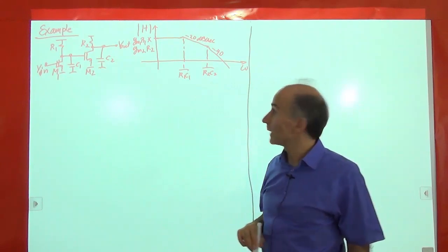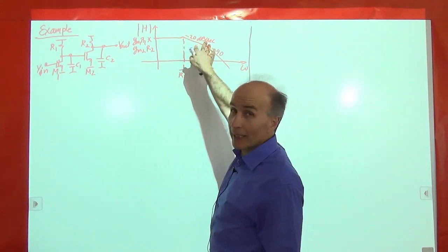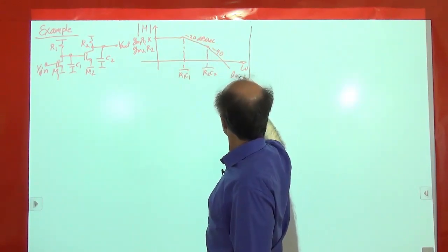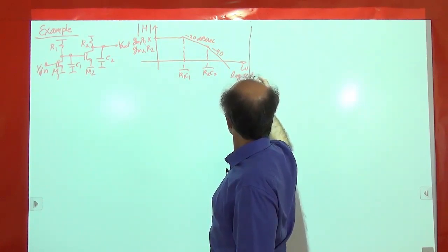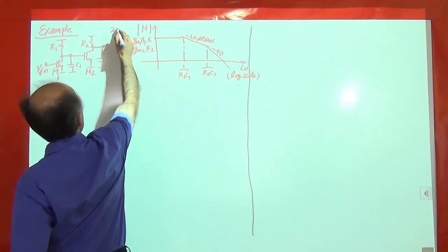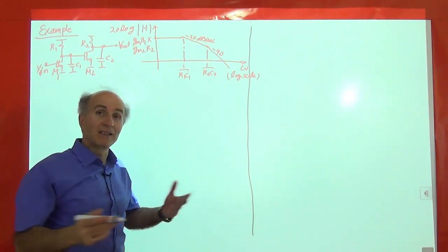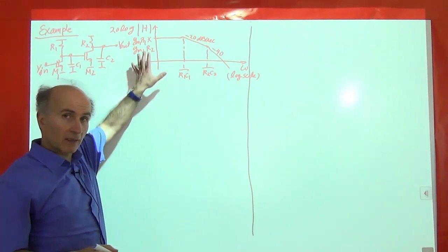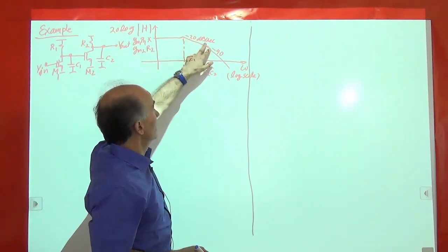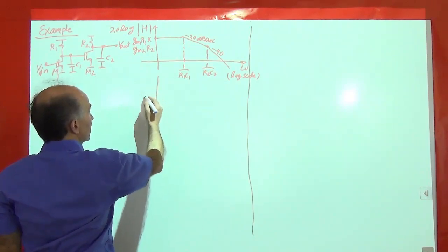In practice, for these to make sense, when you say this is dB per decade, this is dB, this is decade. So this should be a log scale, the horizontal axis. And the vertical axis also has to be log scale. So it's 20 log of this, so the result is in dB, in decibels. But that's how we would do it precisely if we really want to get this to be 20 dB per decade and so on.